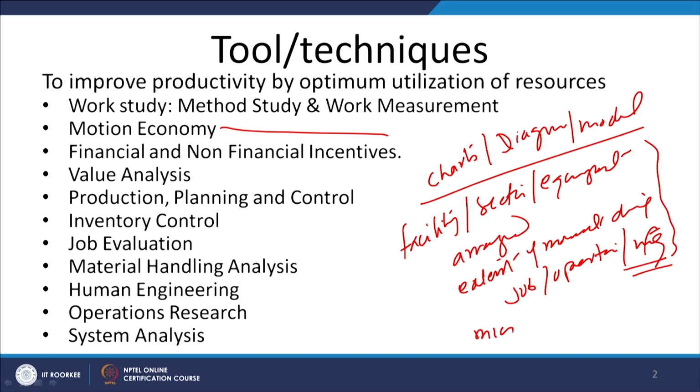In that case the micro motion study tool is used, which helps in investigating and studying the actions of the different body parts during the job, and identifying if there are non-productive elements present in the existing method of doing a job, and then what kind of improvement can be realized after micro motion study of the short time jobs, so that the efforts to do the same job can be reduced, and the time to complete the job is also reduced.